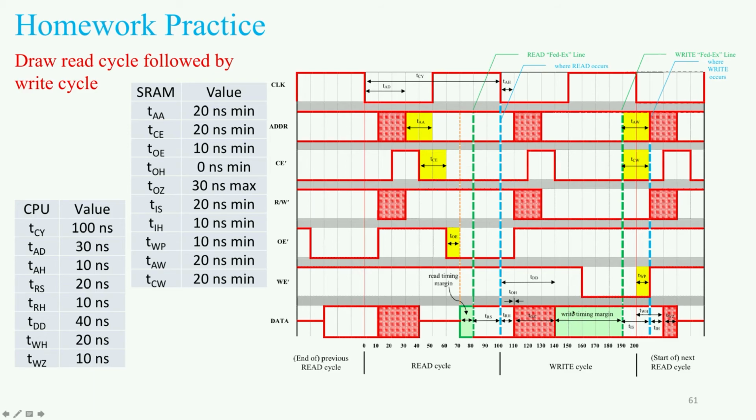Now the SRAM is going to effectively be reading in the values on the data bus. Okay, so the data is valid by this point. You've got the write bit valid. Remember, the SRAM is not actually reading this bit, it's actually just reading both of these bits. The write enable bit is valid by this point. Chip enable is valid. The address is valid. The data is valid. So by this point, the SRAM is basically sucking in all the values that are on the data bus and storing them to the correct address in the SRAM.